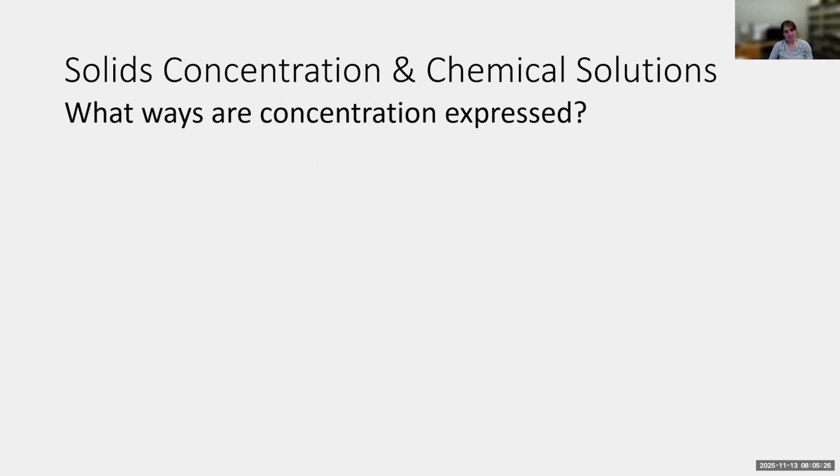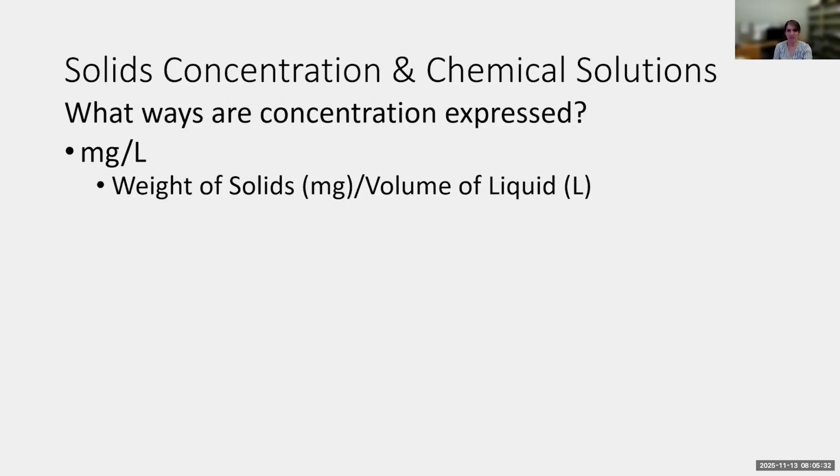What are the ways that concentration can be expressed? Well, we just talked about milligrams per liter, which is weight of solids over volume of liquids. We can also talk about it in terms of parts per million, which represents the number of parts of a substance per 1 million parts of the total mixture.